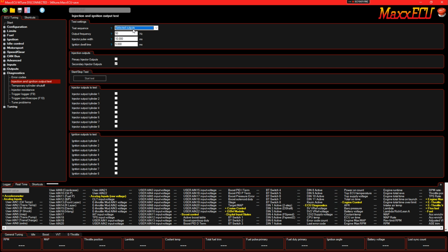So if I was going through, I would put on selected outputs, your frequency, your injector pulse width, your ignition dwell time, and you can go in here and just select each individual one that you want. You'd hit start test. You can test that one, test that one, test that one. And that's for your injectors, and you can go down here and test your coils. Make sure all your coils are clicking. Very nice to make sure, especially whenever you first get your car up and running, that everything is actually working.